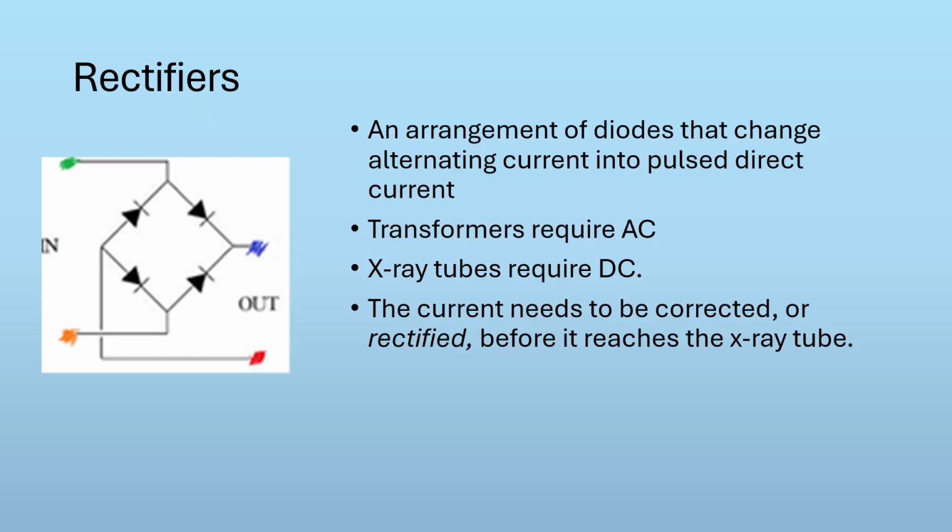And let's bring the positive charges in from orange, and again, the positive charges have to go to the right and exit at blue. So what we have is AC input, but DC output. The positive charges always end up at blue, the negative charges always end up at red, and it's the diodes that are steering the traffic.